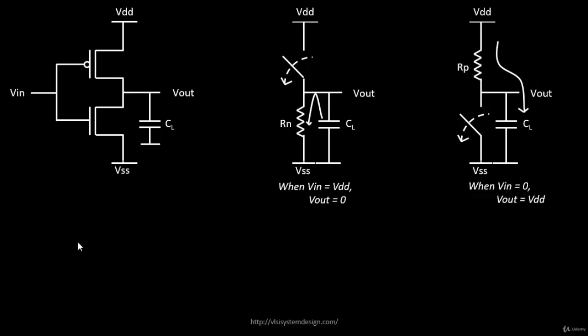Okay, so the next part is the naming convention. We just need to give some names to these nodes, because eventually we'll be writing a SPICE circuit for this one, and therefore we need the node names. So let's try to do that. We'll call this the gate, this is the source, this is the drain for NMOS, and again gate, drain and source for PMOS, and their respective connections.